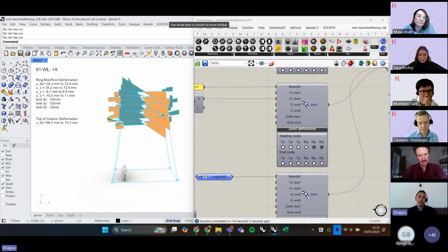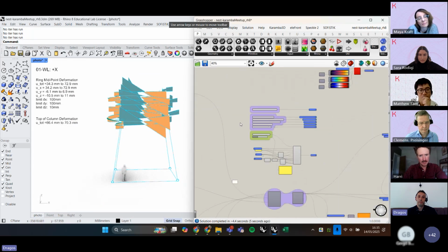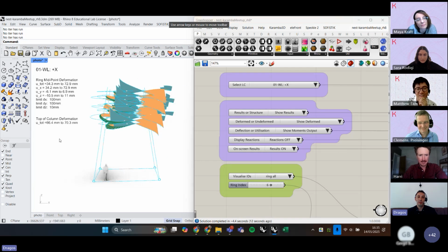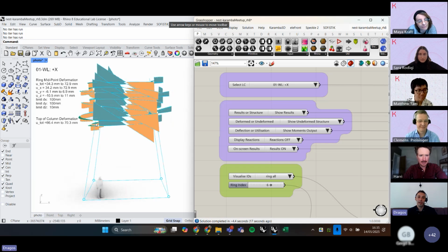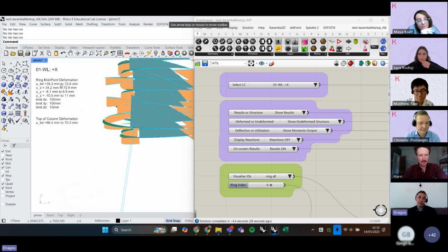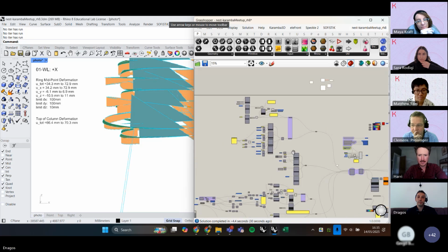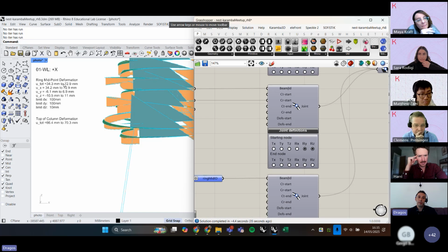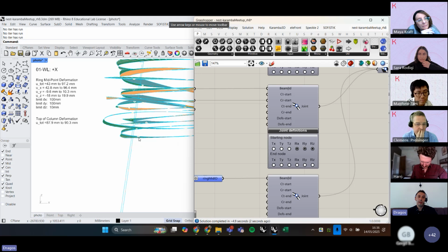So if you look in the wind X direction, sorry, I'm getting a little bit into the details of this, but this is wind X. You can see the portal frame action being clearly built. So all these rings are trying to transfer moment into the columns, well, into that arm, and the arm is welded to the column. The deflection is limited to 73 millimeters, whereas if you actually release it, it increases to around 93, I think, but the moments basically disappear there.